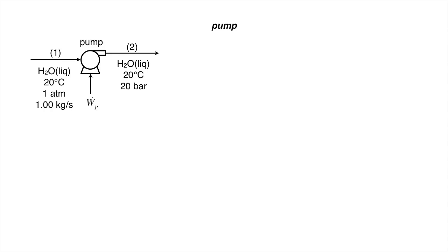Okay, with those more laborious calculations out of the way, let's take a look at the pump and calculate how much power we're using. Those of you taking Chem E 330 right now might be doing this kind of calculation. But we can also handle it with an open system energy balance. If we assume the pump operates adiabatically, the pump power must balance the change of enthalpy from streams 1 to 2, with a total extensive value proportional to the total mass flow rate, m dot H2O.